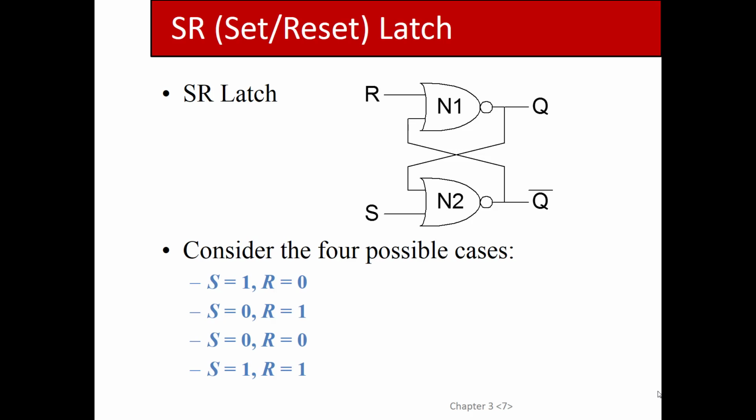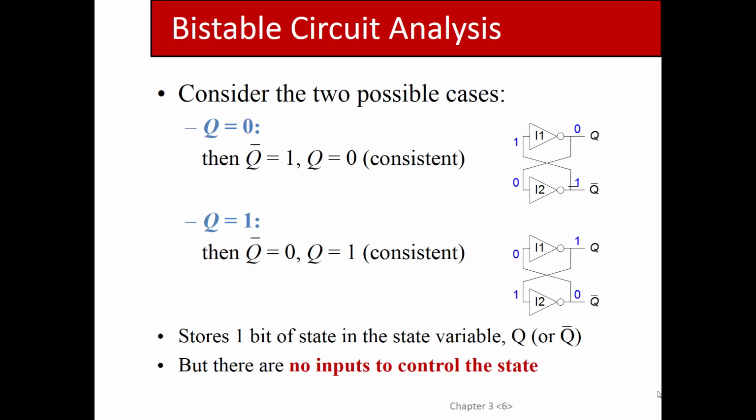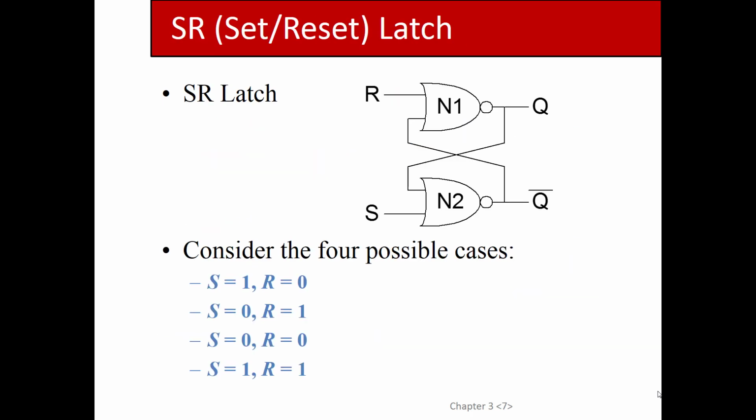So this becomes a cross-coupled inverter. That's what I'm trying to say. So it ends up becoming equivalent to this, right? In other words, a 0, 0 will capture a value in here, and it will make it persist because these guys will essentially become inverters, right?